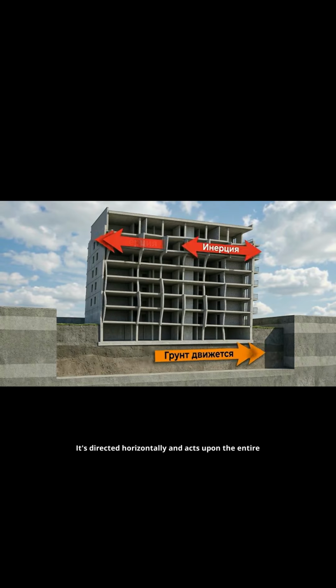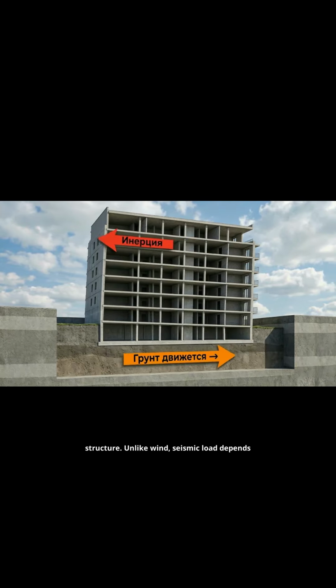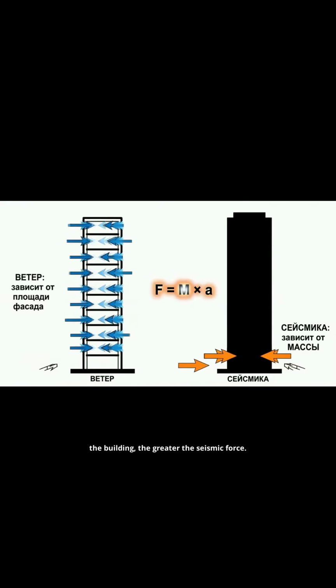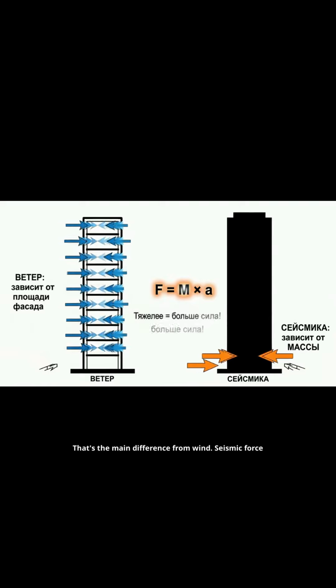It's directed horizontally and acts upon the entire structure. Unlike wind, seismic load depends primarily on the mass of the building. The heavier the building, the greater the seismic force. That's the main difference from wind.